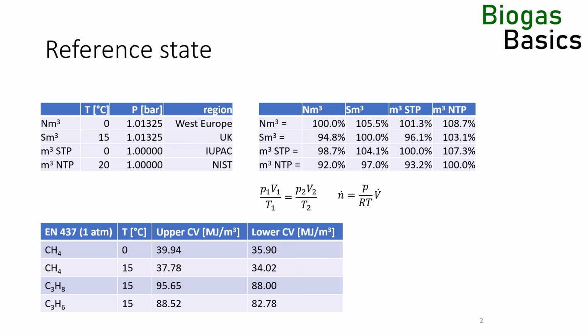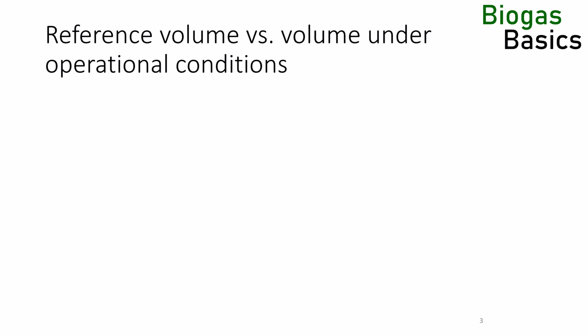Now let's go back to the impact of humidity. While gas yields are generally given at a reference state, for example in norm cubic meters, 0 degrees Celsius, 1.013 bar, dry, the gas in the digesters has a different temperature, pressure and humidity. The impact of the pressure on the biogas density is very low as a biogas plant typically operates around ambient pressure. Temperature has a higher impact, as biogas can heat up in the headspace of digesters, especially under dark gas domes when the sun is shining.